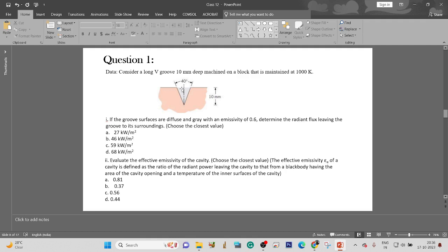Now A1 F12 is equal to A2 F21. We already know that about the view factor. We'll use this, and F21 is equal to 1, obviously. From surface 2 to 1 it will be equal to 1. It is enclosed, and surface 2 is completely visible to surface 1. So F21 is equal to 1, and from that we can clearly calculate, if we consider this as a